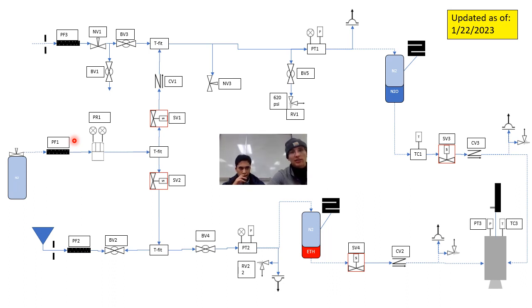It keeps nitrous oxide a liquid, even at relatively high temps, like 20 degrees Celsius, not actually high, but nitrous oxide is normally a gas at room temperature. So we pressurize it to keep it a liquid. It's also pressurized to keep a constant driving force on that nitrous oxide during the test, so that it's forced into our little injector holes and into the combustion chamber where it can combust.